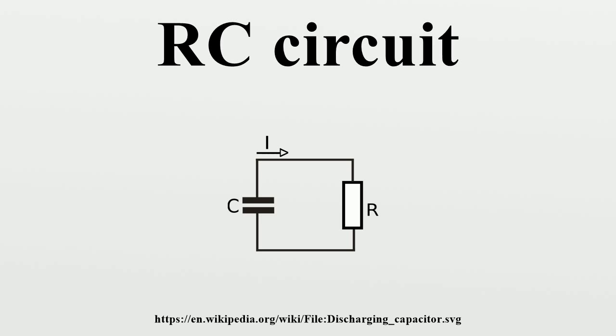These equations show that a series RC circuit has a time constant, usually denoted τ, being the time it takes the voltage across the component to either rise or fall to within 1/e of its final value. That is the time it takes to reach a given level and to reach the other. The rate of change is a fractional 1/e per τ. Thus, in going from t = τ to t = 2τ, the voltage will have moved about 63.2% of the way from its level at t = τ toward its final value. So C will be charged to about 63.2% after τ, and essentially fully charged after about 5τ.